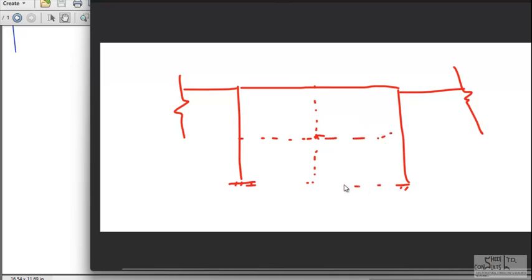So the equivalent force that will act on the joint, if the total area is enclosed and there is no opening whatsoever, right? The total force divided by 4 will give you the joint loads at these joints. Okay?